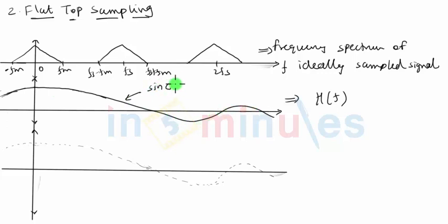This is nothing but that sinc signal which we have got, sinc(f tau), with obviously the constant value of tau, which will decide the magnitude at 0. But what we have drawn is a proper sinc function. When I only consider the magnitude spectrum, in that case this negative lobe will become positive. Let H(f) be as it is as of now.